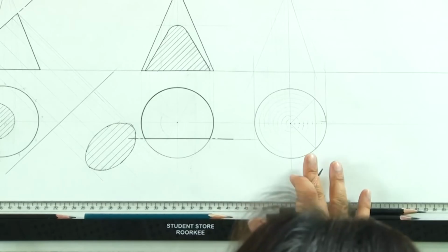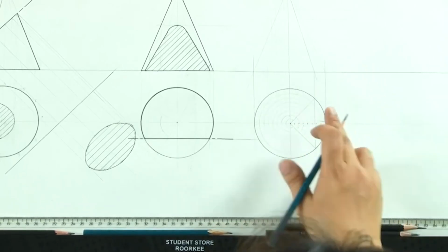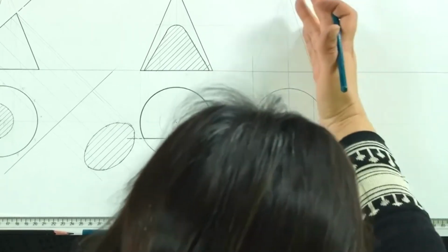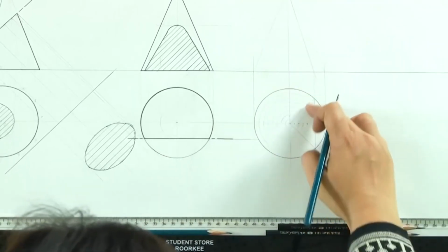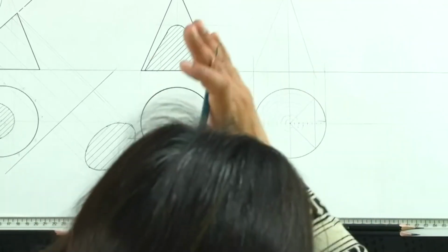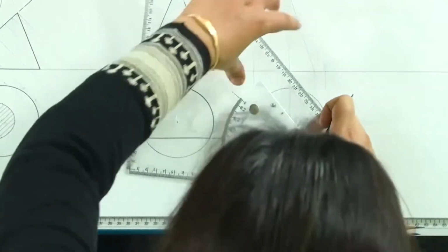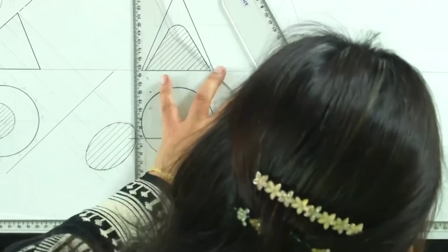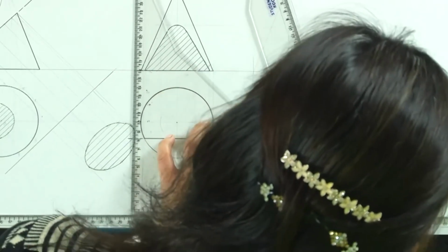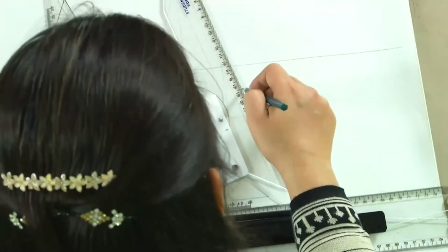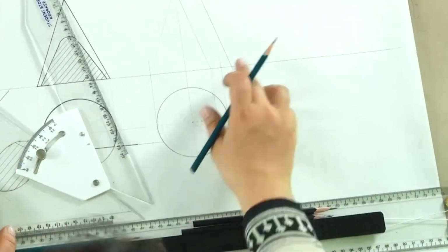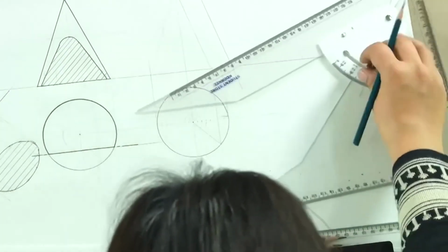So, if I want to now draw the true shape of the section which is going to be parallel to this, because in top view we will only be getting to see this triangle, and in the front view we will only be getting to see this straight line. So, let us try to draw the true shape of the section here. I am fixing it parallel to this section plane again, and I will now take the projections.